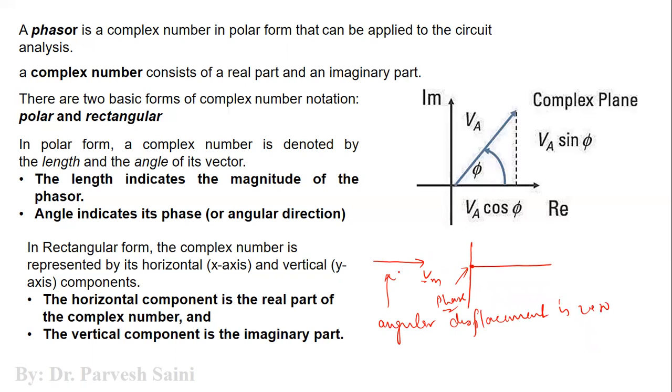All right. Now the other one, which is the current phasor. Current has some phase which is 5 degrees behind the voltage. So it will start from here, this point. This is the magnitude here, and the phase can be taken as 5 degrees behind. So it will start like this. You have a reference phasor sine wave, and it will remain 5 degrees behind. So this would be the phase difference.